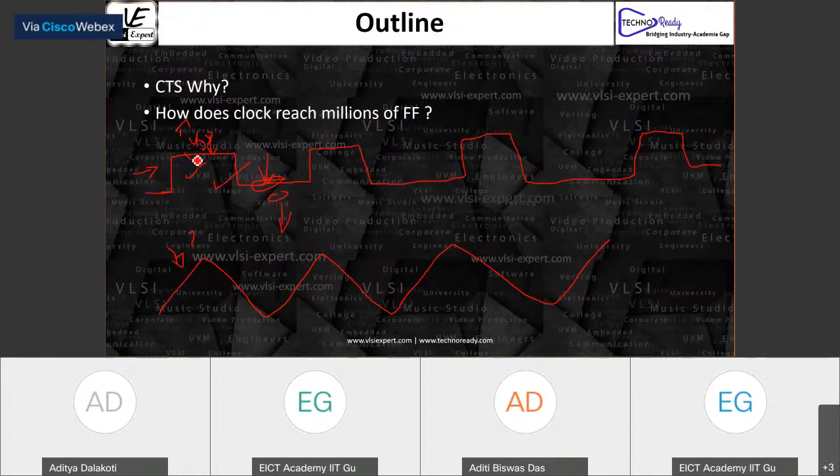So noise doesn't have effect in these regions, or has a very minimal effect. Noise has effect in these regions where you are not at VDD or ground, where your power supply is not actively pulling you in one direction.